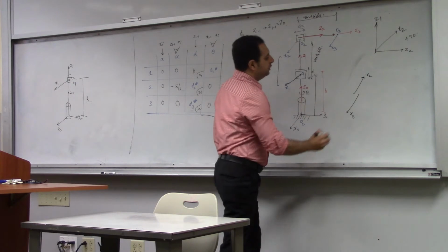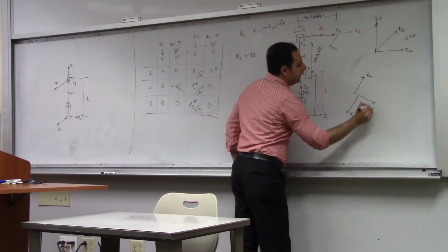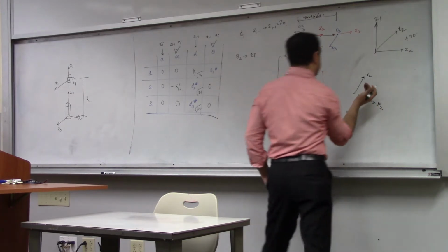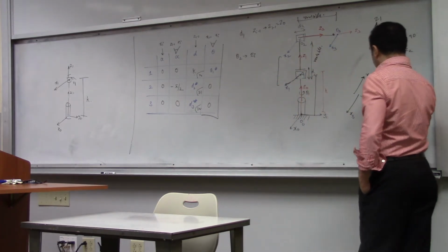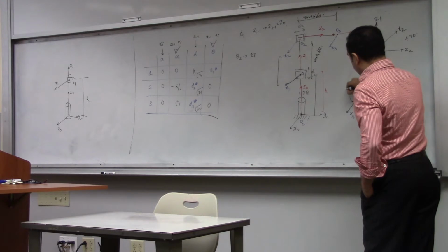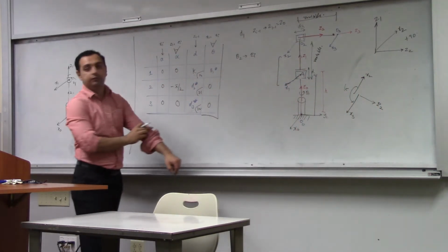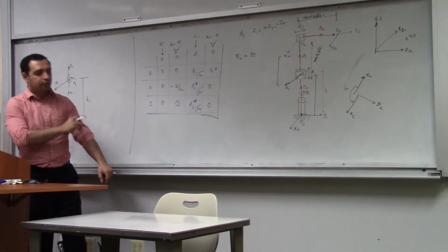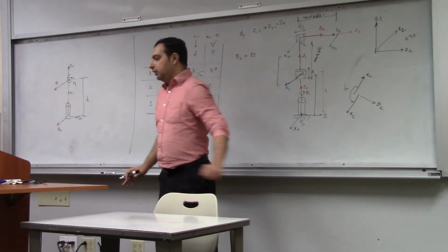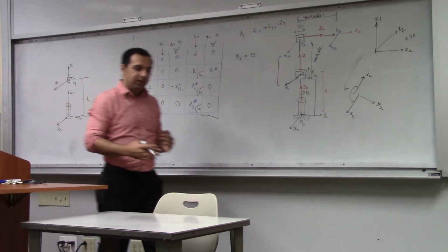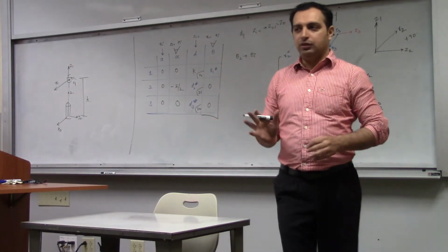right? And you measure theta along Zi minus 1. Zi minus 1 is Z2, right? So you measure along Z2 like this, so the angle from here to here. All right? Professor, why are you ignoring the y-axis? Okay, good. So that is one of the drawbacks of this notation, that you cannot measure any displacement or any rotation about the y-axis.